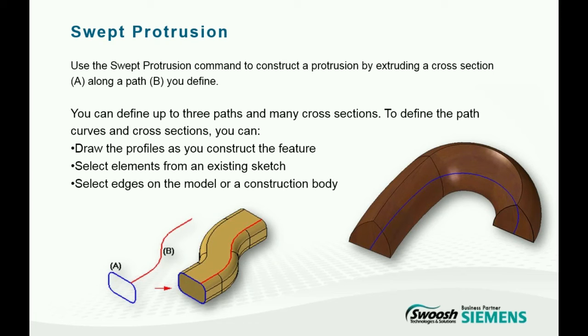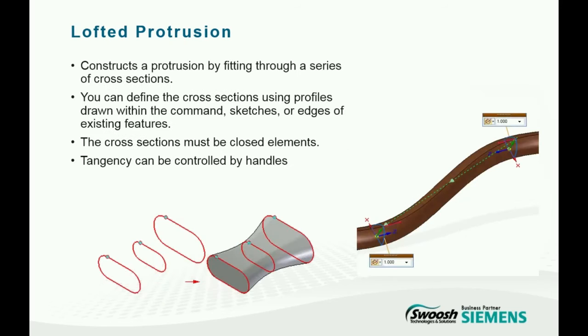And even if you choose, I'm going to show you in the settings, a single guide curve, single section curve, it will still require a guide curve. So it allows you to quickly and efficiently connect maybe existing designs or add advanced geometry. It can connect existing geometry, as I mentioned, or you can utilize newly created sketches on the fly.